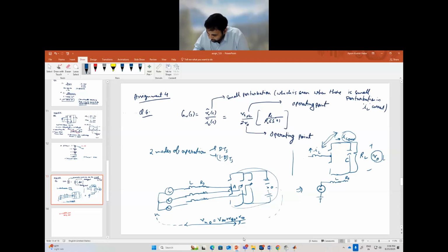On the other side, this is the VDC, the common mode voltage, which is always a DC value. And on the other side you will get your VAO voltage, which is the converter voltage, this is my Vs of t voltage, and this is my common mode voltage.